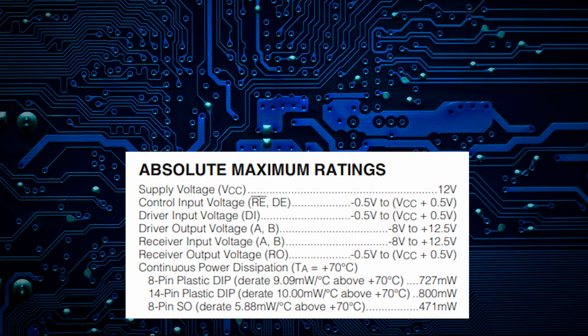The interface capacity runs up to 4,000 feet in length, which equals 1,219 meters, giving us a significant advantage over long distances. The datasheet indicates that it has ESD protection up to 15 kilovolts, which is usually the standard in interfaces intended for long distances or industrial purposes.